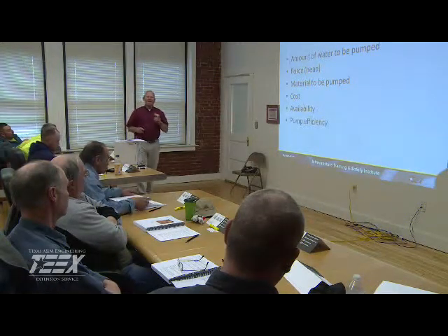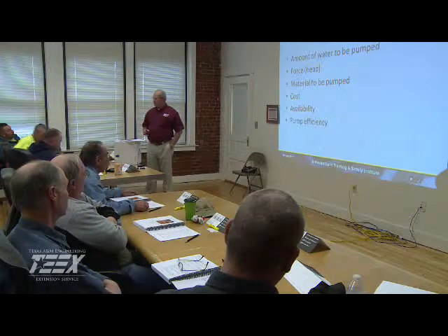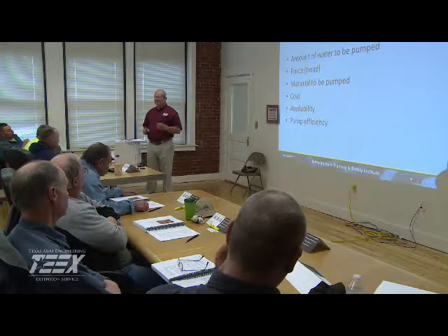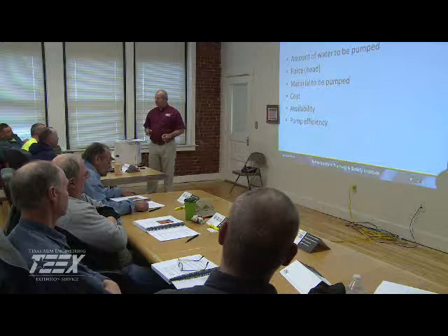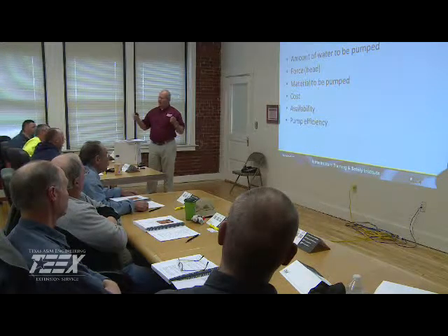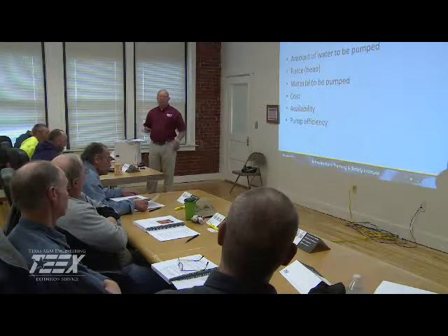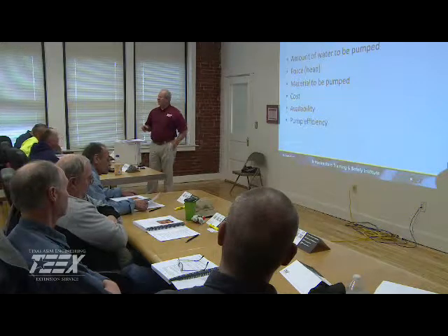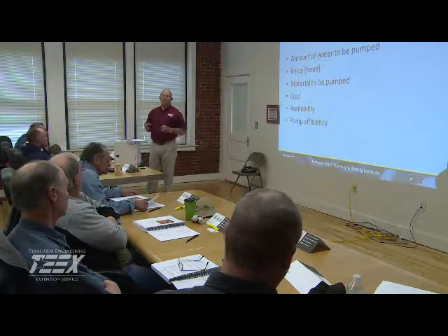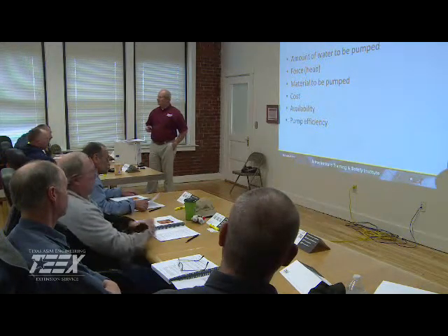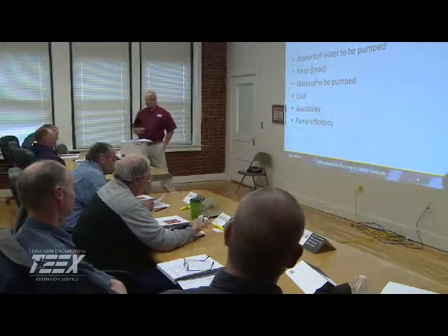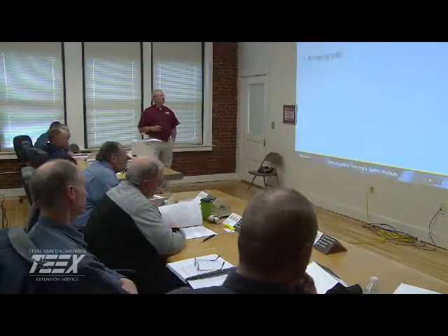Do not buy a low efficiency pump. The reason is, if it's 80% efficient, then you're going to have more horsepower, larger pumps, to do something that a smaller pump could do with a higher efficiency with a much smaller motor. Okay? You got to take that into consideration.